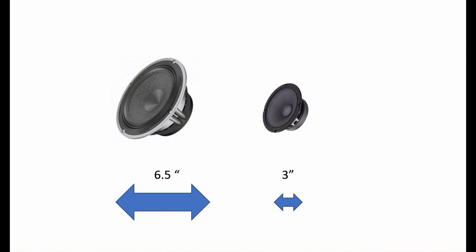So what that means is if you're using more power, you're going to be generating more heat. You need more air moved per speaker stroke, but the strokes are much slower. So if you think about the little 3-inch, compared to 1,000 hertz, it's going to be moving 10 times slower. The cone area and the excursion of the speaker cone hasn't changed, however, but at some point, this little 3-inch is not going to be able to move enough air or deal with enough power to play super low notes, right?